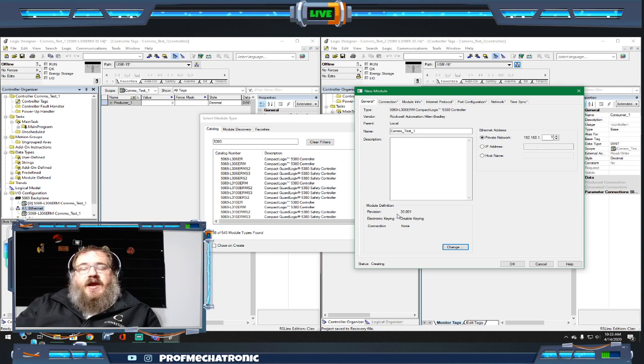And the numbers on the right-hand side of the dot are our minor revisions. In the PLC world, the major revisions are key. You have to make sure your major revision always matches. The minor revisions aren't as important. Most of the time, what that does is just clean up some of the issues, clean up some of the communications, clean up some of the faults and garbage that happens on there. So you don't have to really worry about that so much.